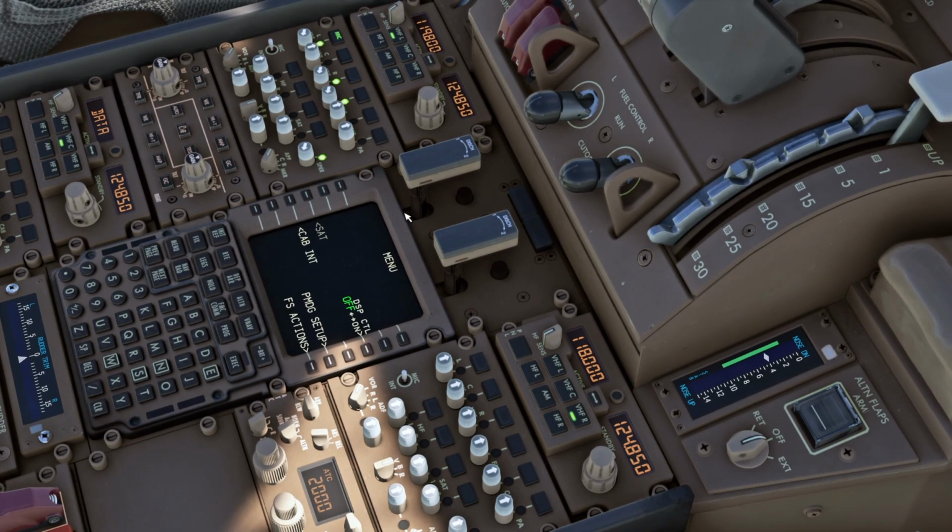Then we go up here. Here we have the engine fire panel. Verify that the engine bottle 1 and engine bottle 2 discharge lights are extinguished. If any of those bottles, which is used for fire extinguishing, has a low pressure, it would be indicated here. It would require maintenance to refill that, of course.